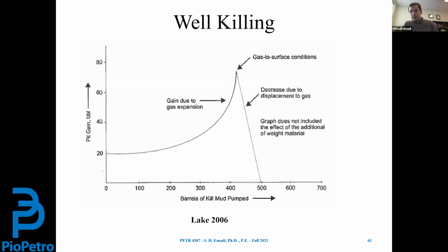Thank you, Maya, for the introduction. So this is the last lecture on the introduction to well control. I think the last session was 3 weeks ago, and I was talking about the two well killing methods, the wait and weight and driller's method, and how the pressure gauges on both casing pressure and standpipe pressure behave during the circulation.